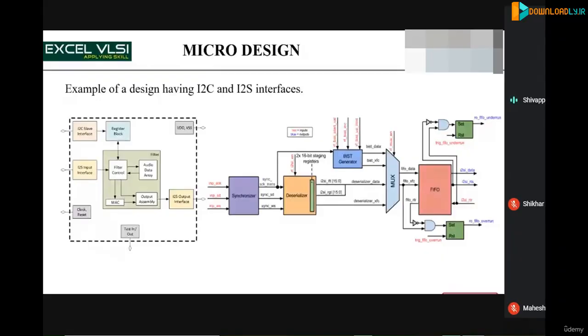And I2C or I2S, these are serial interfaces. Means what? One bit at a time. Okay, so then internal processing within the chip you will do with parallel processing with 8-bit or 32-bit or whatever, right? So all those things, when you're sending it out, you may be serializing. So now and then this BIST, DFT, and the multiplexer and the FIFO and the flip-flop.